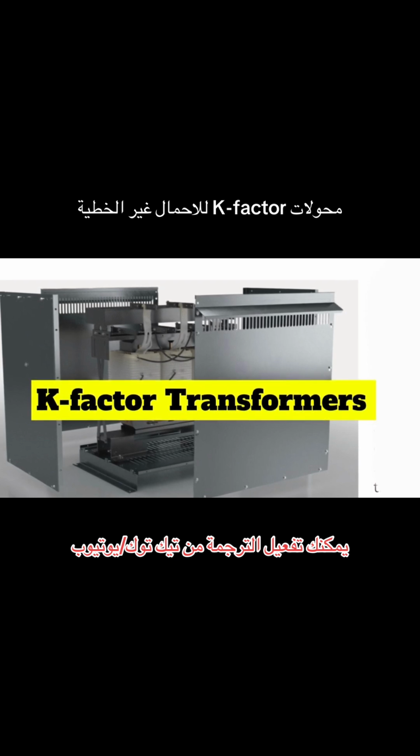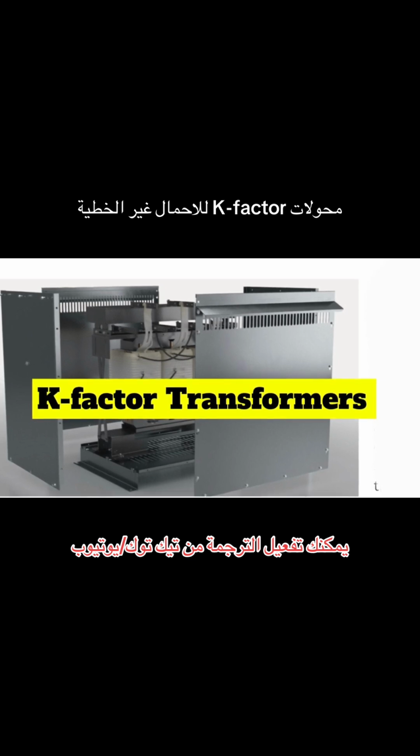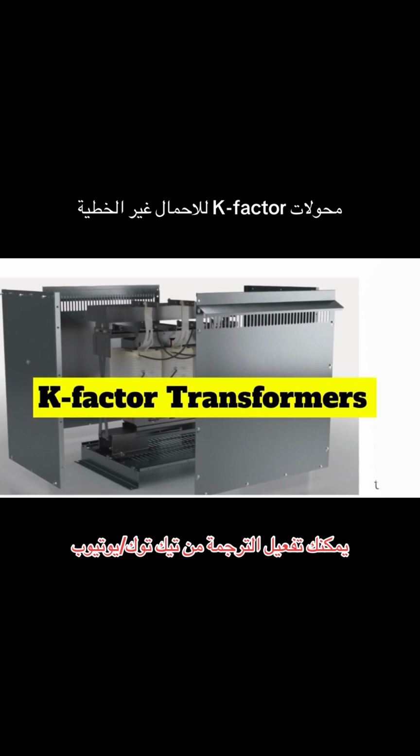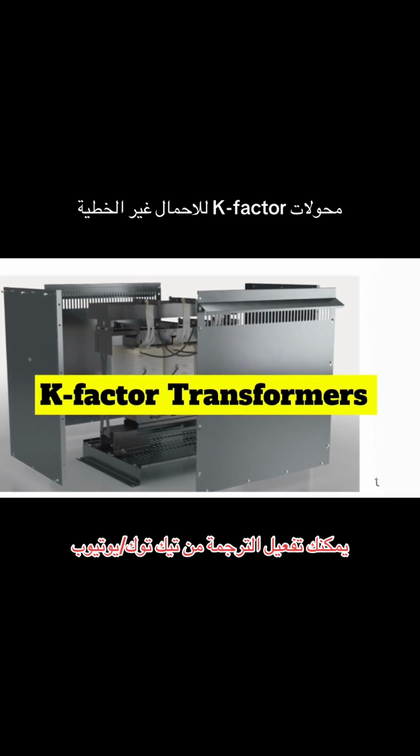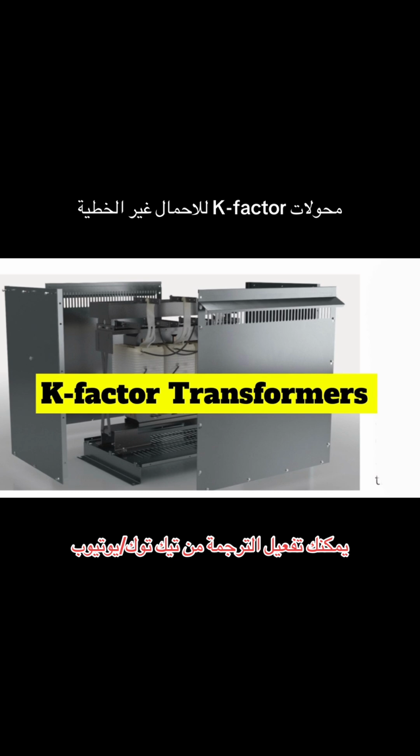Then you move up to a K4 rating. This is often used for things like induction heating equipment, SCR drives, and AC variable frequency drives. These systems are used to control motors precisely and efficiently, but they can generate a fair amount of harmonics. In these applications, you might have up to 50% of the connected load producing significant harmonics. So K4 is for the more sophisticated motor control systems you see in a lot of modern buildings, right?